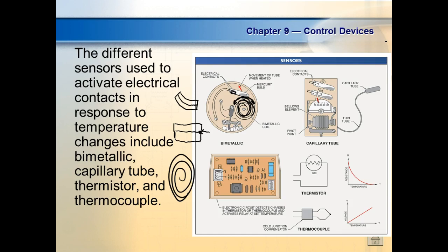Now what that thermocouple is doing is allowing the main gas valve to open. So that way if the thermocouple is not good, or if the pilot light's not lit, it won't turn on the gas. Just because your thermostat up here, which is electrical, right? It's powered in your house. So it controls the valve, but the electrical signal off the thermocouple prevents the main valve from opening if there's not a pilot light.